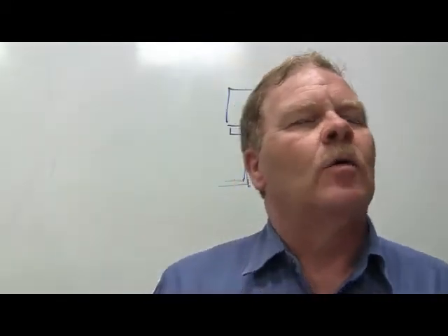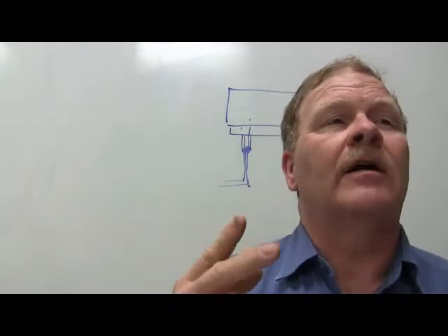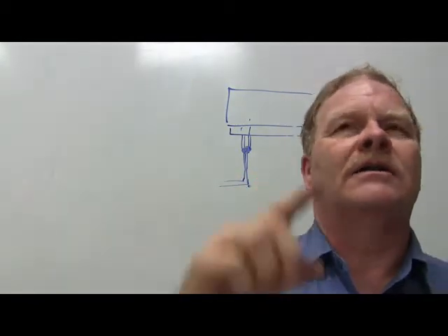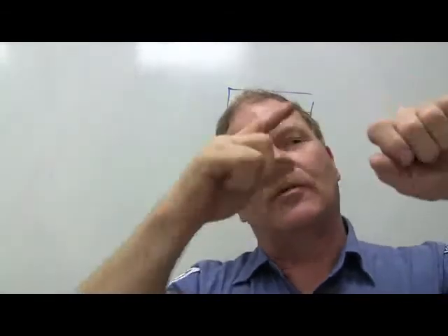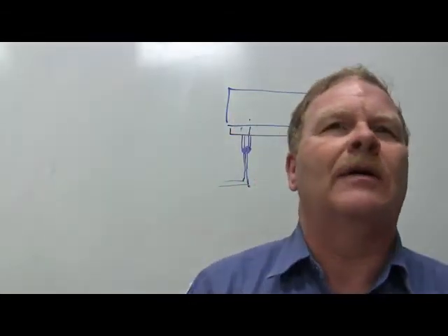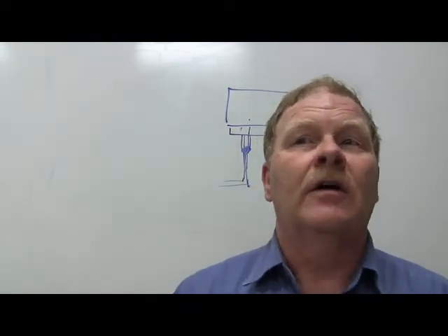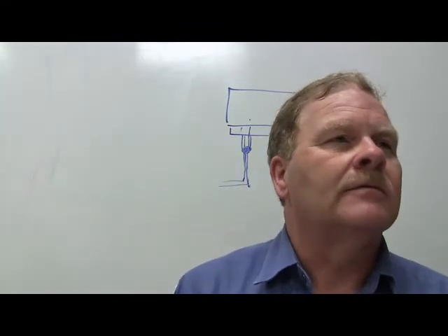Those wires will have foil wrapped around them. They'll be twisted around one another. They'll have foil wrapped around them, and they'll also have a wire that lays along next to them, so that wire is touching that foil all the way up and down, and they ground that wire, and that prevents electrical interference from getting in there. You got me? I just put that poster up there.